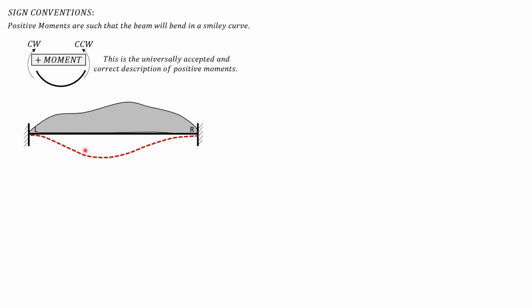Here, this is similar in shape as this. But at the walls, we expect negative fixed end moments or bending. So at the left end, because this is negative, the direction is counterclockwise. So we have negative moment there, negative moment there. So this should be counterclockwise. This is opposite to that.